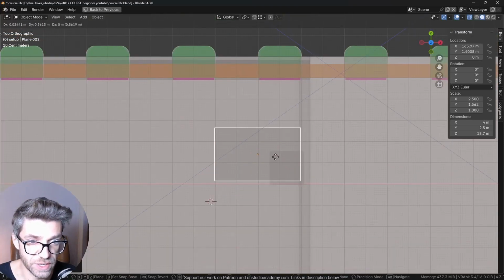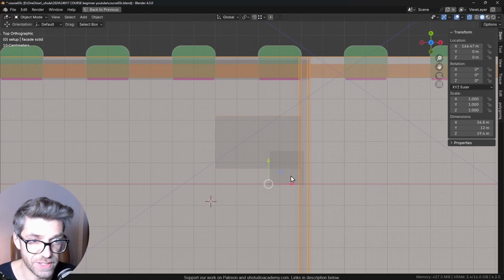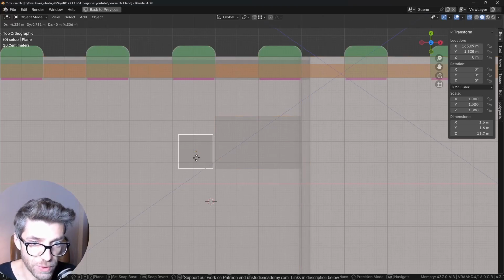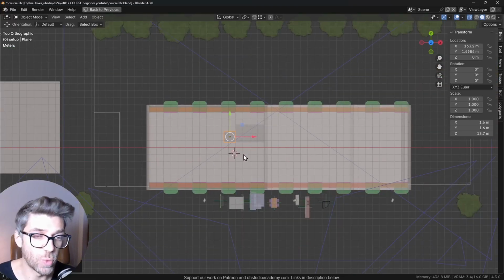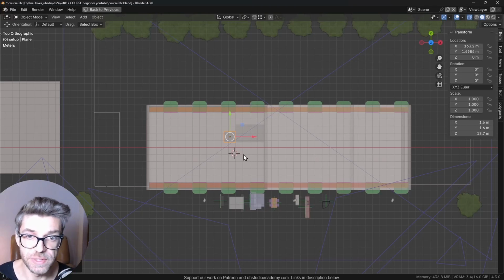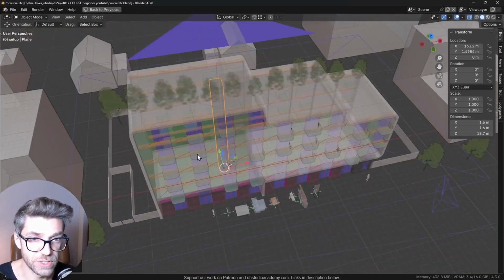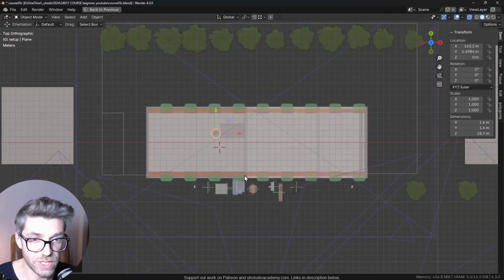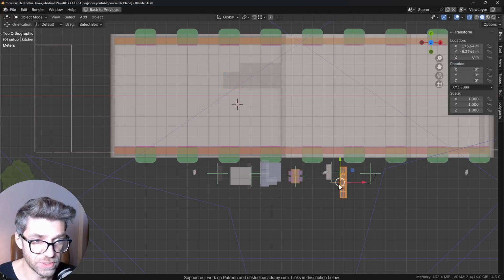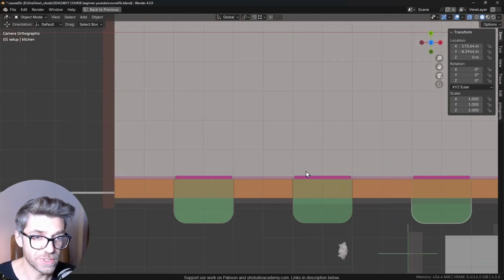So this is the center line. So from the center, we're going to have a corridor that's about 1.4 meters wide, so that needs to come over here. So right away, I'm noticing our building might not be wide enough. So what I'm going to do is just model one side for now. And then depending on, yeah, we can really easily adjust the width of this actually at this point. But we need to start doing a bit of layouts to understand whether the scale is correct or not. And before we do all those layouts, we need to start doing some walls.